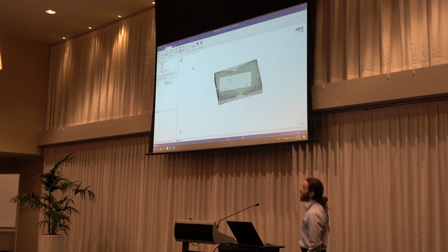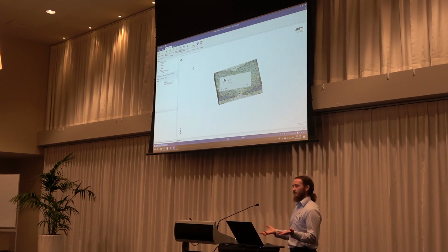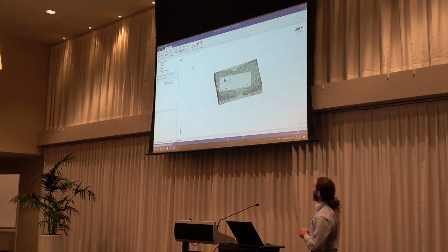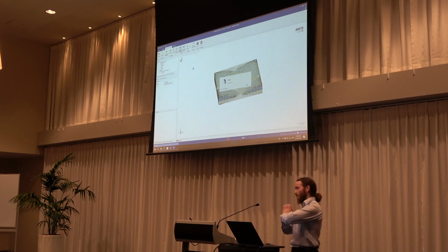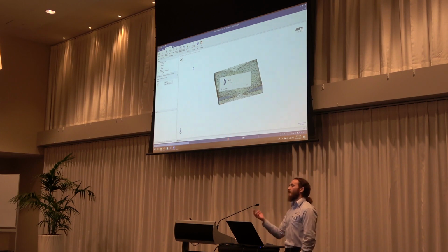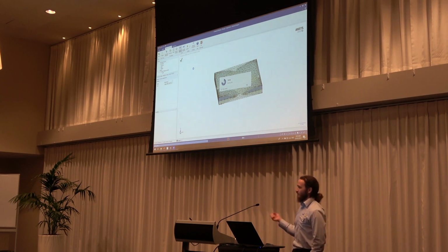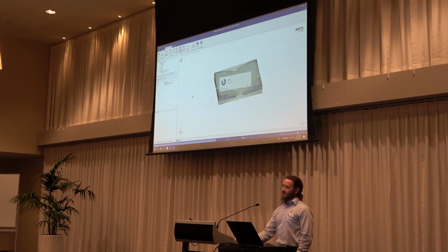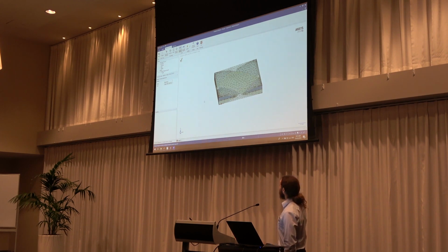So you can see it's all sort of pre-canned and automatically set up, so I don't have to create geometry or anything. I can just specify the rough material constants. So it's very useful for someone who's doing composite layups where our materials post-layup don't really match the standard material property data. So when you get material properties for, say, carbon fiber in resin, it's for a particular fiber volume fraction. And your manufacturing process may give you a slightly different fiber volume fraction, which will give you very different mechanical properties. So to get a good FE model, you need to have the correct mechanical properties. So we can use this to calculate that for us.